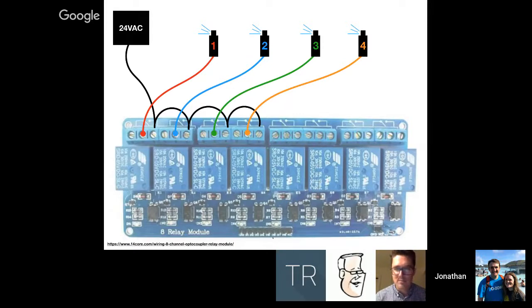Oh, so the pins go in that bottom connector. Yeah, at the very bottom of this relay picture, right in the middle, there are these little black rectangle looking things. These are where all those pins are. Okay. And on either end, there's a ground on the left end and a VCC on the right end. That powers it, and then all these other pins are the triggers, and they correlate to a number, which relay it is. Got it.